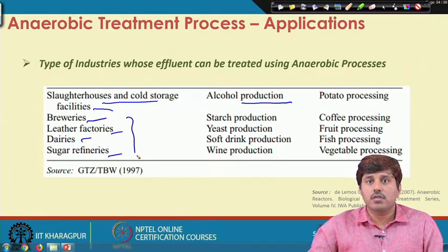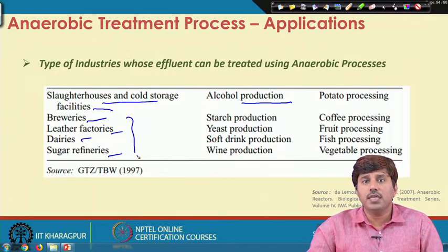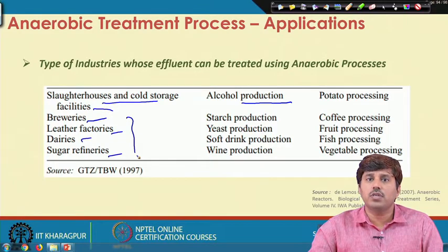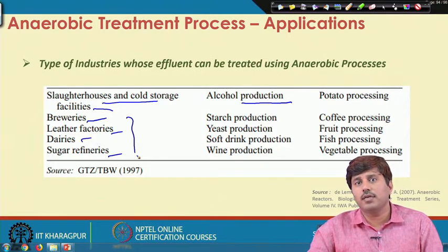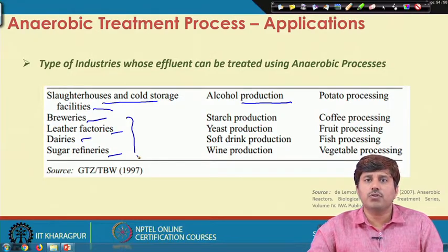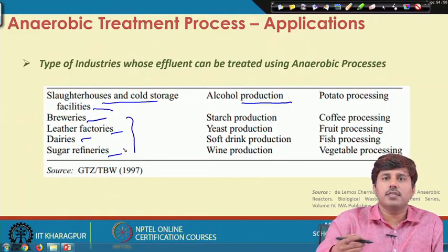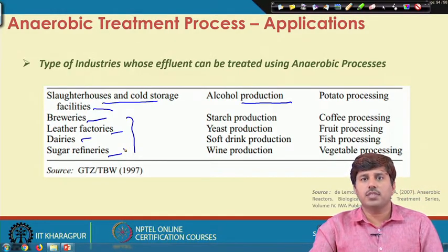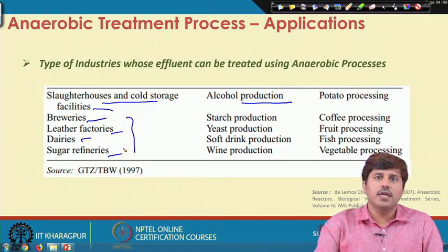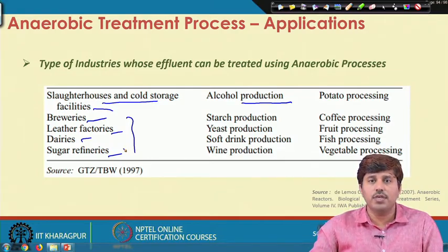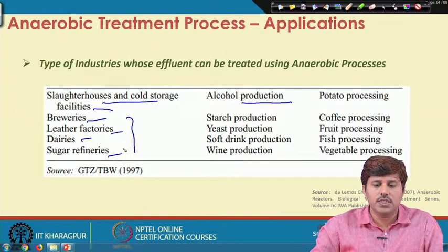Now, imagine the kind of aeration requirement if you want to degrade 2 lakh COD with the activated sludge process. That is going to be a hugely costly, intensive process, and if an anaerobic system which is 60%, 70% efficient can remove 70,000 of COD without much cost, it is always a welcome step. So, that is how these are used.